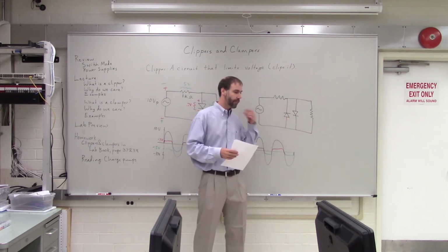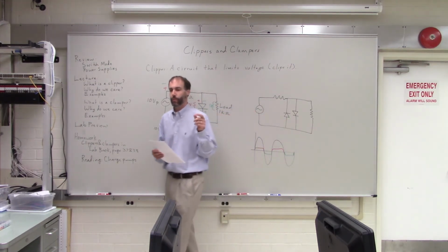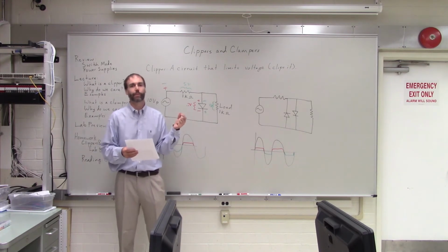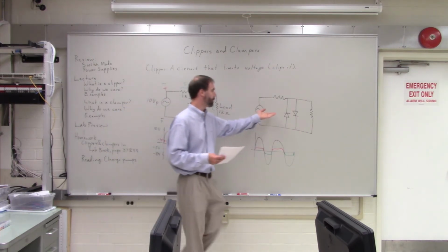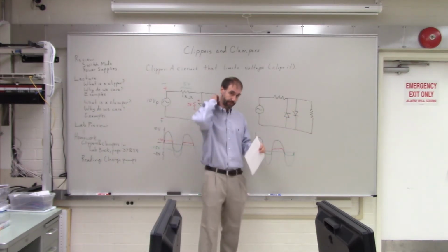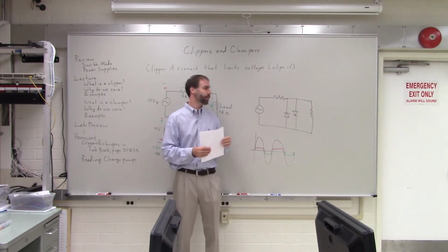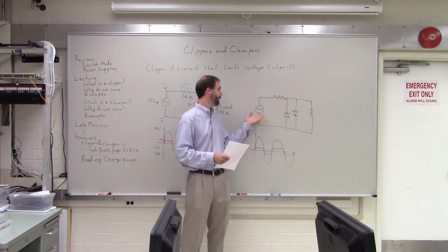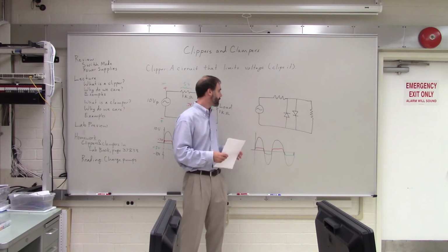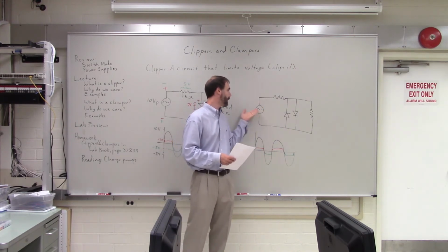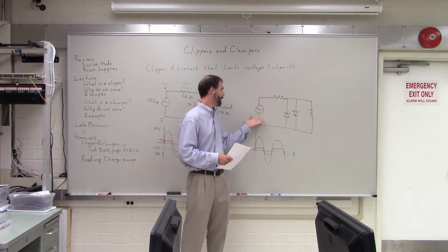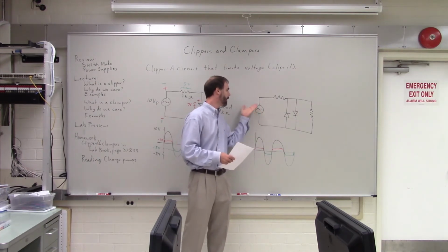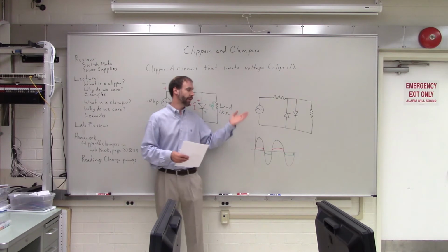They normally expect signals in the range of maybe 0.1 volts maximum. So if they saw something as big as 0.7 volts, that would be about the max that they could handle. So they have a circuit kind of like this which handles any big spikes that might be coming from this AC source. And this AC source might be like an antenna in the case of a radio.